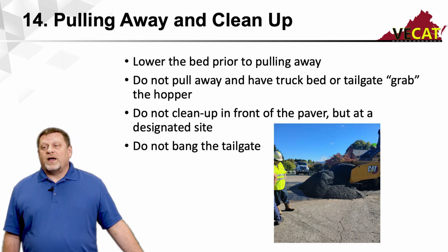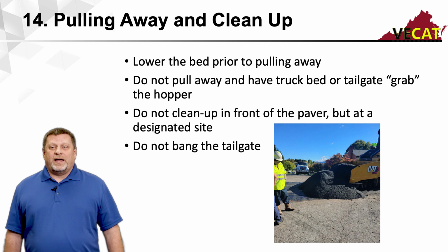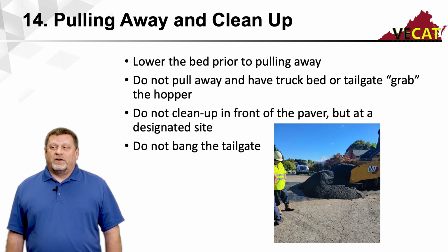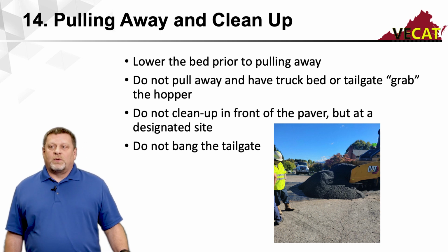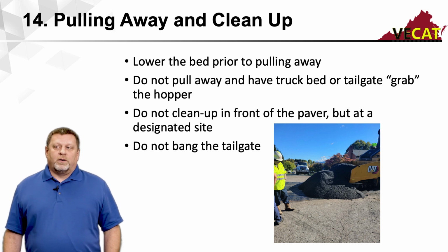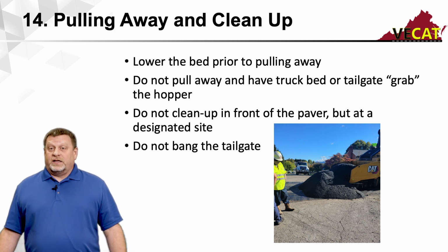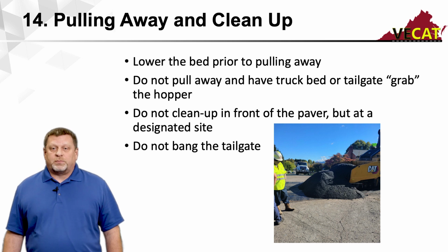And once he pulls away, a lot of people have a tendency to bang their tailgates and clean their bed out in front of this paver. We don't want this debris, or small pieces of asphalt, to fall in front of the paver. It's important what we're placing our mix on be very smooth and uniform. So it's better if you have on your job site a designated area to clean your truck beds out. That also allows at the end of the project only one spot that has to be cleaned up before you move on to the next project.